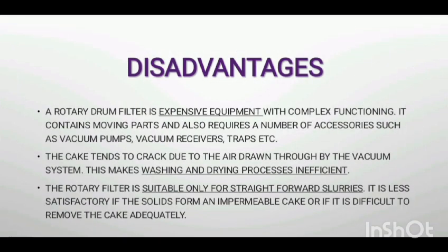A rotatory drum filter is an expensive equipment with complex functioning. The cake tends to crack due to high air drawn through by the vacuum system. This makes washing and drying process inefficient. The rotatory filter is suitable only for straightforward slurries. It is less satisfactory if the solids form an impermeable cake or if it is difficult to remove the cake adequately. Now let us see a video in which the rotatory drum filter is shown, which is used